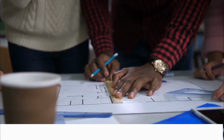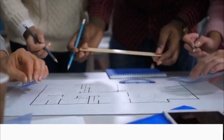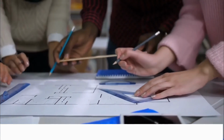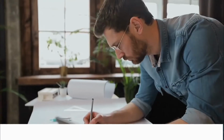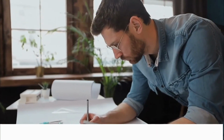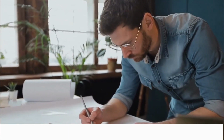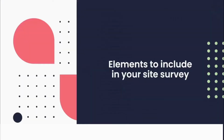If you find that you are missing measurements or missing elements of the survey, or something's unclear or incorrect, you will then need to go back to that site and rejig your site survey or reassess the site survey. So as you can see, it's incredibly important to double check on site that you have everything. So when you go back, you're not wasting time having to go back to the site again and remeasure everything. From here, we are going to take a look at some of the elements that you need to consider and include on your site survey.